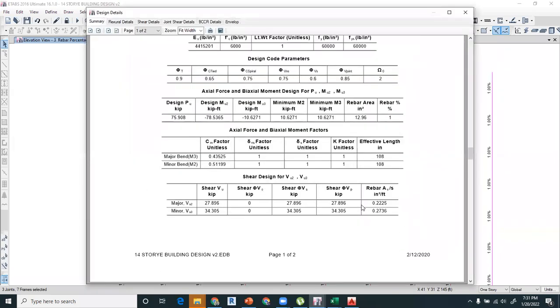So at the top, there is a requirement of shear reinforcement because the acceleration and the story shears are greater at the top. So the shear area is asking about, you can see that phi Vc is equal to 0 because if the demand is greater, then it takes the shear capacity of the concrete equal to 0 and then gives you the reinforcement in the column.